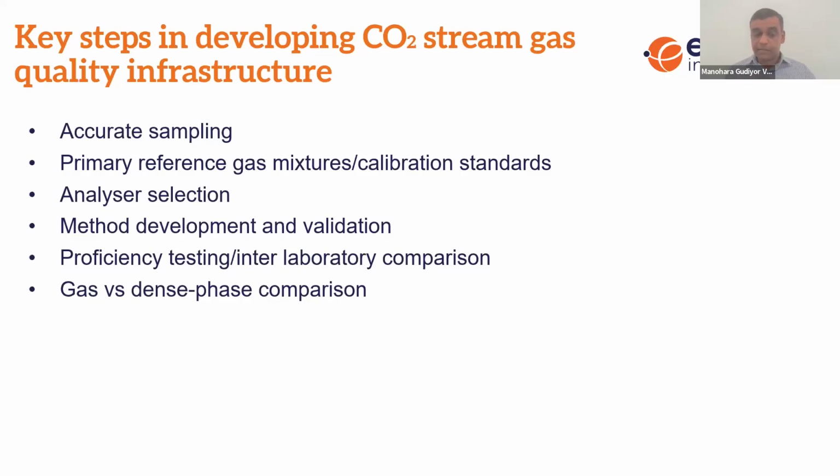But in dense phase, we don't have anything which we can measure at high pressures, around 82 bar and above. That's something we all need to consider when doing CO2 purity analysis. This is not part of this guide, but I thought it's a good example to give of an additional challenge you need to consider while doing CO2 purity analysis. Next slide, please.